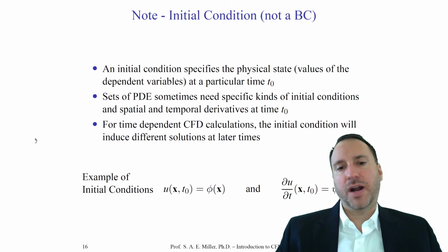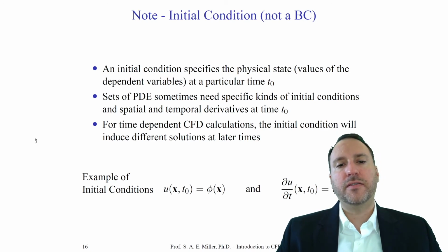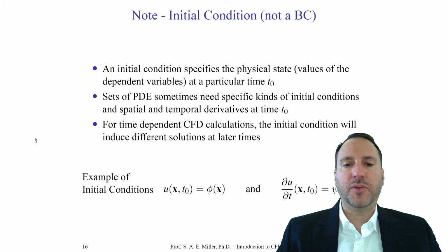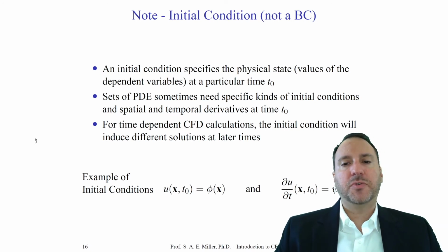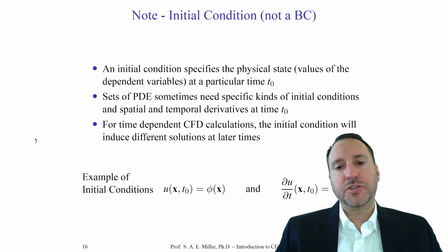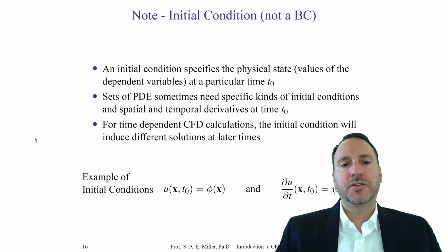Now, steady problems do not typically require initial conditions in computational fluid dynamics. They're only dependent on the boundary conditions themselves. They're called boundary value problems. Time-dependent problems would be called initial condition problems or initial boundary value problems. So be careful.